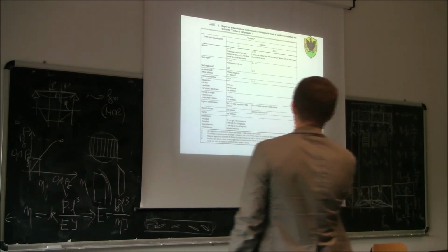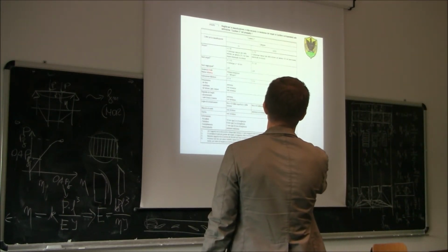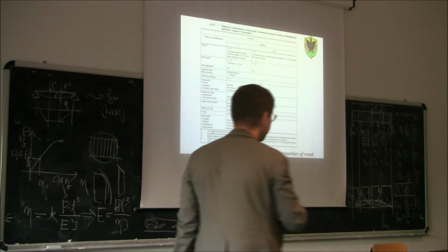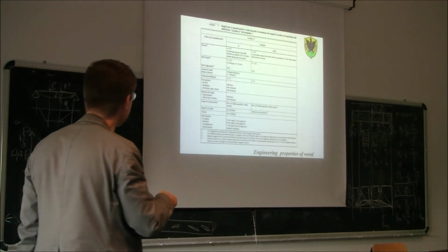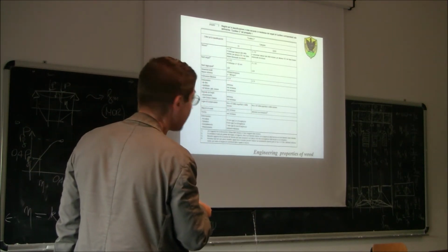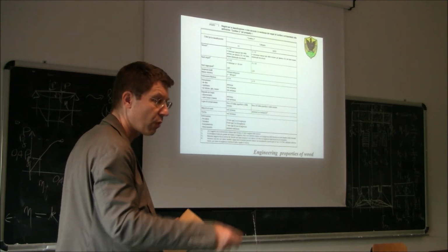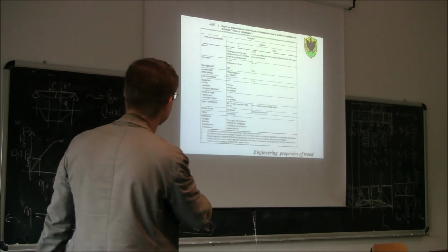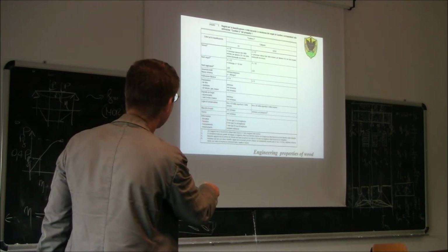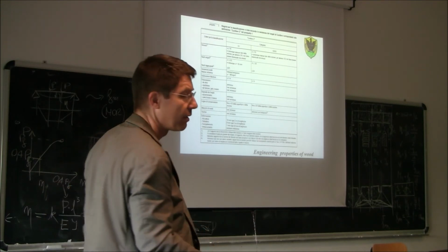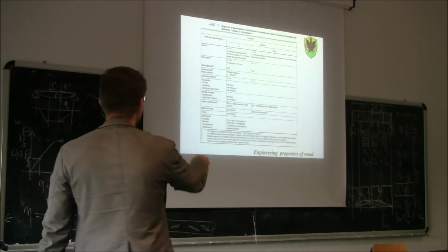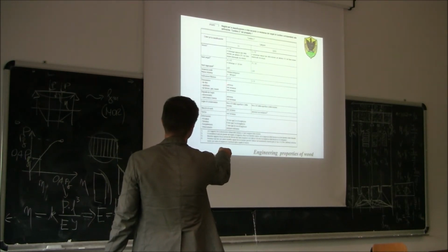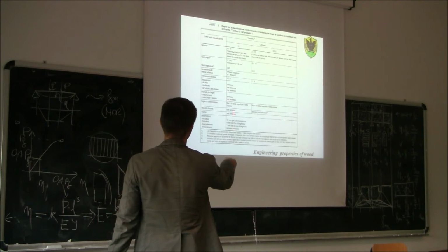This is a group of knots. This is the width of the growth rings: no limitation. Then here we have the grain deviation. To be S1 it must be less than 1 over 14, so 1 centimeter over 14 centimeters maximum. If it is more than this, it goes to S2. But anyway, also for S2 and S3, it should be less than 1 out of 8. So you need to do all this exercise, and then you see here the cracks from shrinking, these are allowed, the others are not allowed, and so on.